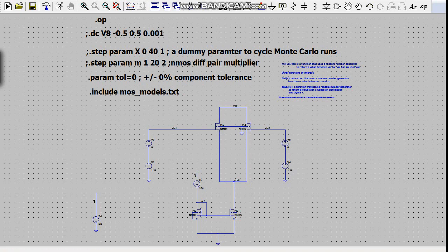Now our purpose is to find out whether the currents in both branches are the same, and how much VGS minus VT is there, that is the initial Von value. After finding this, we will find out how much differential voltage is required to switch current from one MOSFET to another.